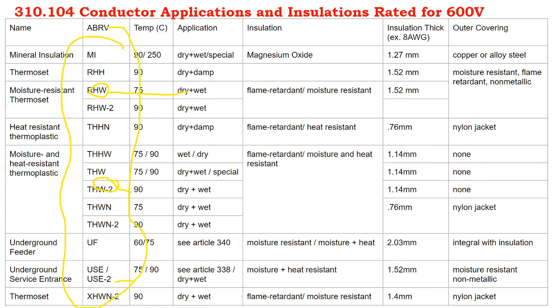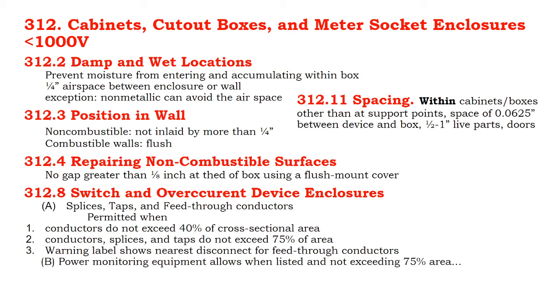So all of these things matter, and they all drive the insulation thickness. Really, non-dry only cable has a less thick cable jacket than your underground service entrance or underground feeder cables that have thicker jackets. So all of these acronyms and product selections mean something.